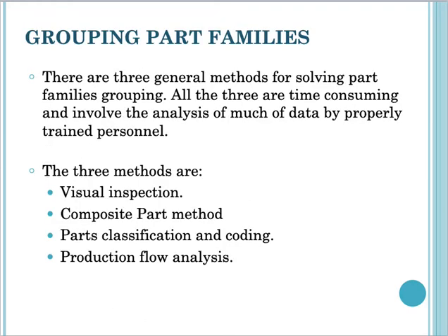And next, grouping part families. There are three general methods for solving part families grouping. All three are time consuming and involve analysis of much data by properly trained personnel. The three methods are visual inspection, composite part method, and part classification and coding, and production flow analysis.